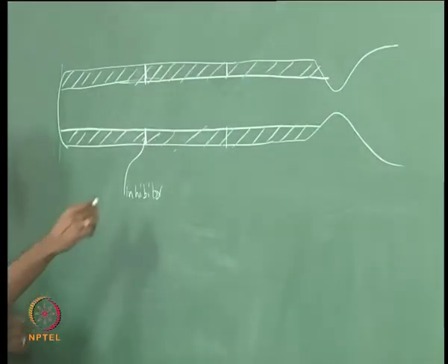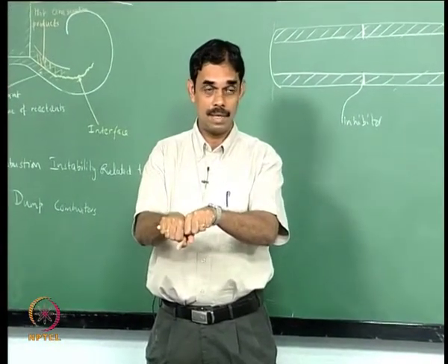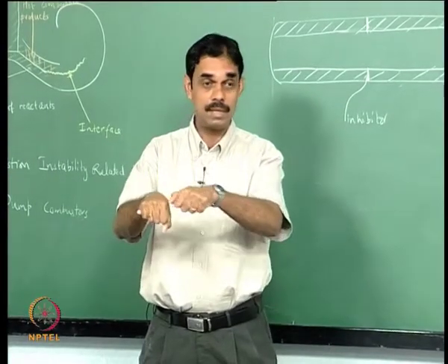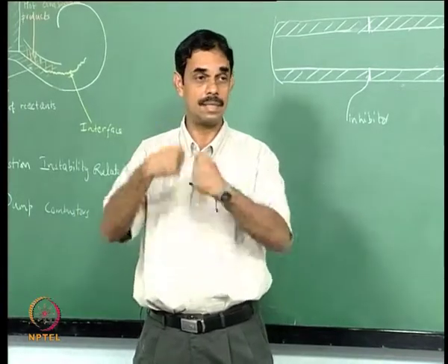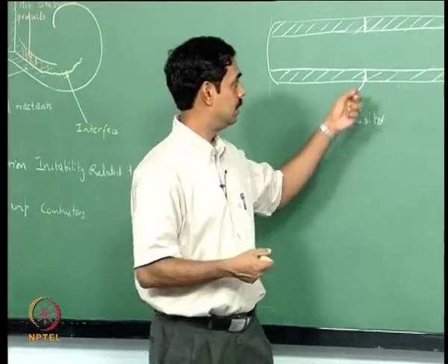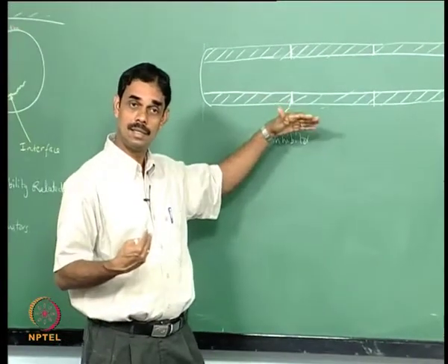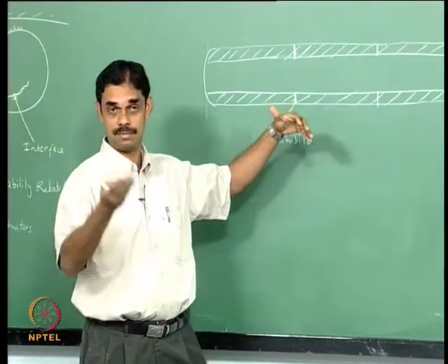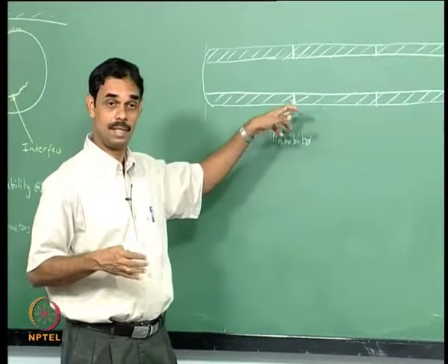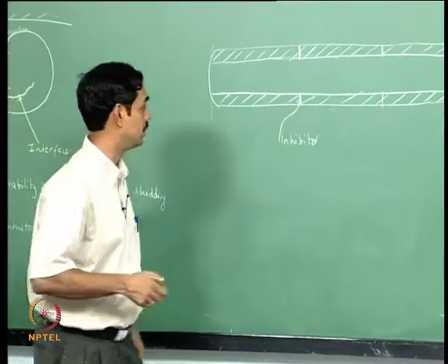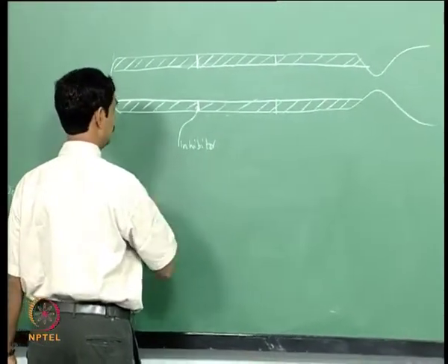Otherwise what will happen is, you can never fit something which is really perfect. There will be some gap, and then the propellant will start burning from the side, and there will be a sudden increase in flow rate. In a solid propellant, the propellant itself is insulating the outer casing structure, as we saw last semester in propulsion class. So we want the propellant there, we do not want the gases to burn and come in contact with the wall, so we put this inhibitor, and then after some time these inhibitors will protrude out.